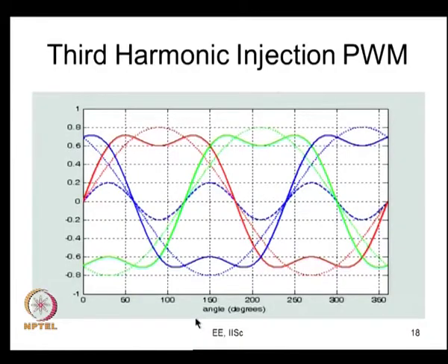In all these, this is some continuous modulation. What happens? There is always a phase switching once. So, sometimes the phase may be carrying a high current, let us say the power factor is near unity. So, the fundamental voltage is high, the duty ratio is high, and the phase current is also high, and the phase is going to switch now. Here the phase current is going to be low, but still the phase is switching once. Here again the phase current will be high, though in a different direction, and the phase continues to switch.